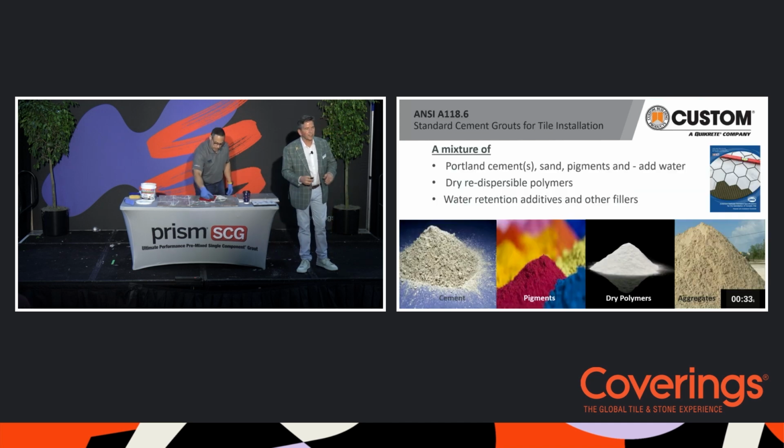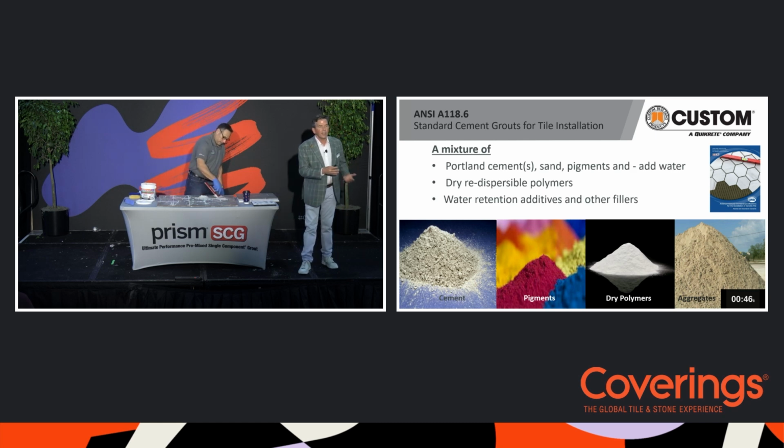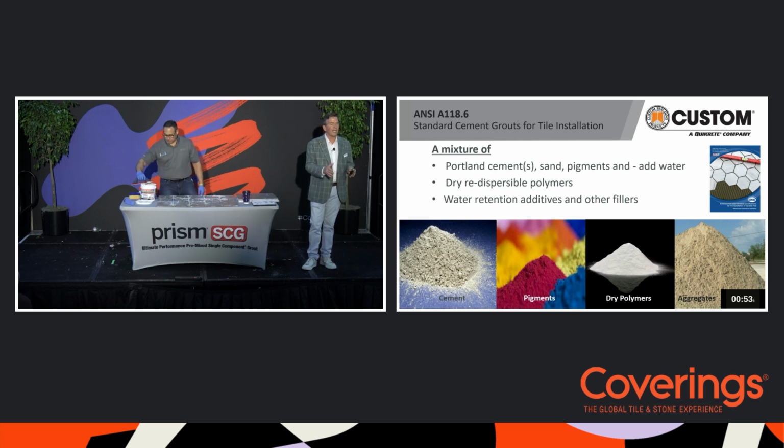The first one is the one we've known forever. That's a Portland cement grout, or a standard cement grout category. This grout's been around forever. It has Portland cement, it has polymers. Originally it was a two-part system, a liquid admixture. That evolved into a dry redispersible polymer so that the contractor only has to add water on the job, not a latex admixture. And it has pigments, iron oxide, and it has water retentive compounds to hold the water in that for the cement to properly hydrate.